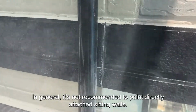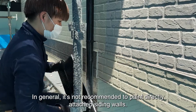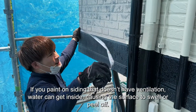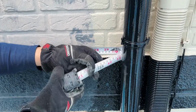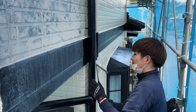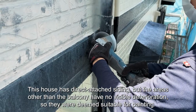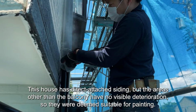In general, it's not recommended to paint directly attached siding walls. If you paint on siding that doesn't have ventilation, water can get inside, causing the surface to swell or peel off. This house has direct attached siding, but the areas other than the balcony have no visible deterioration, so they were deemed suitable for painting.